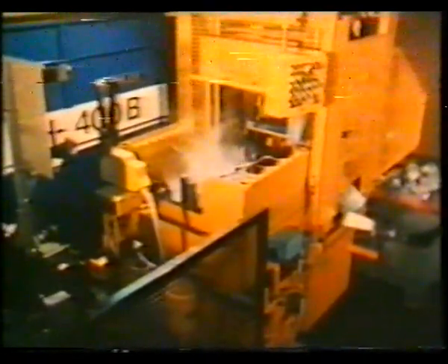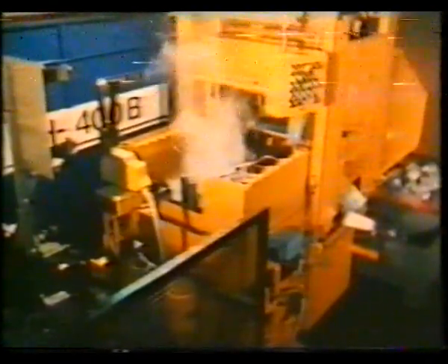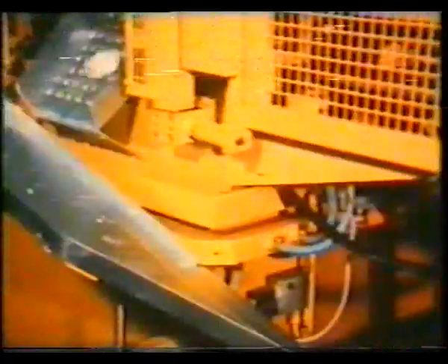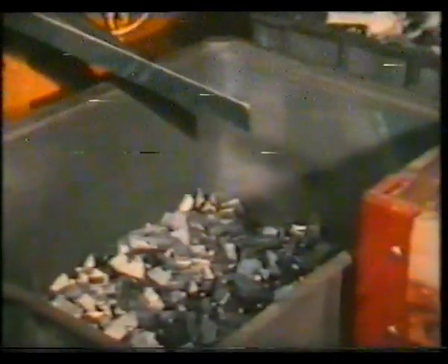The horizontal position of the sliding table and trimming tool ensures ease of accessibility, reducing setup times and allowing good, safe visual control of operation at all times. The trimmings and the castings are discharged separately. The castings are held by the movable trimming tool and ejected onto a tilting plate by a hydraulic ejector.